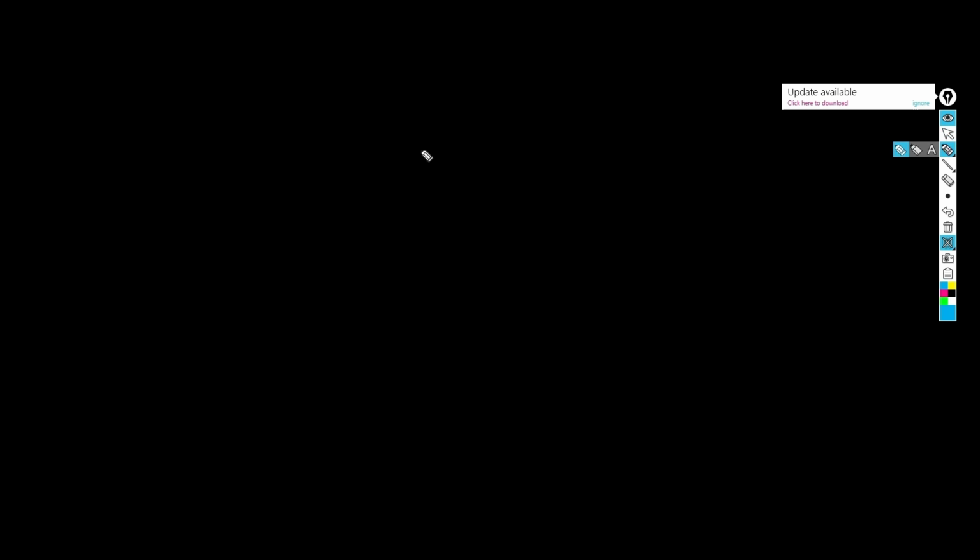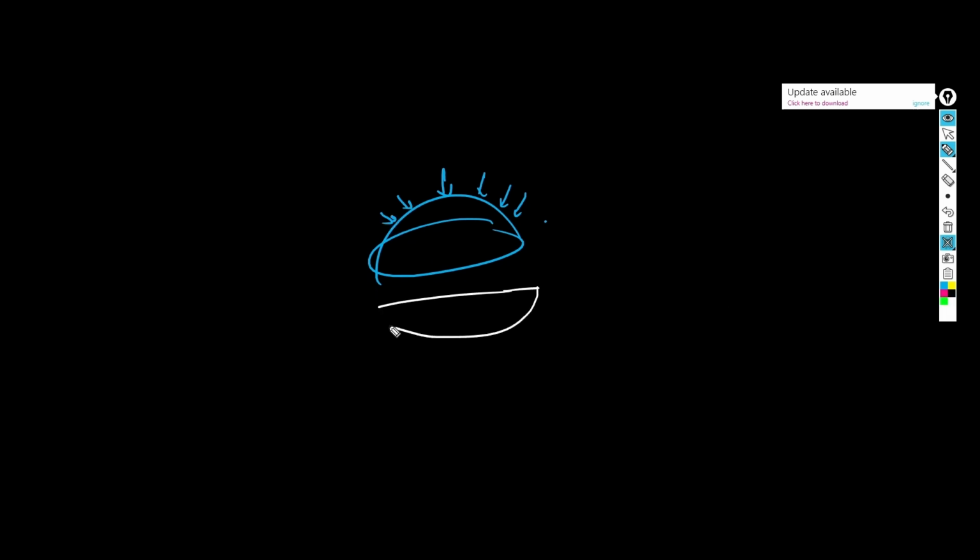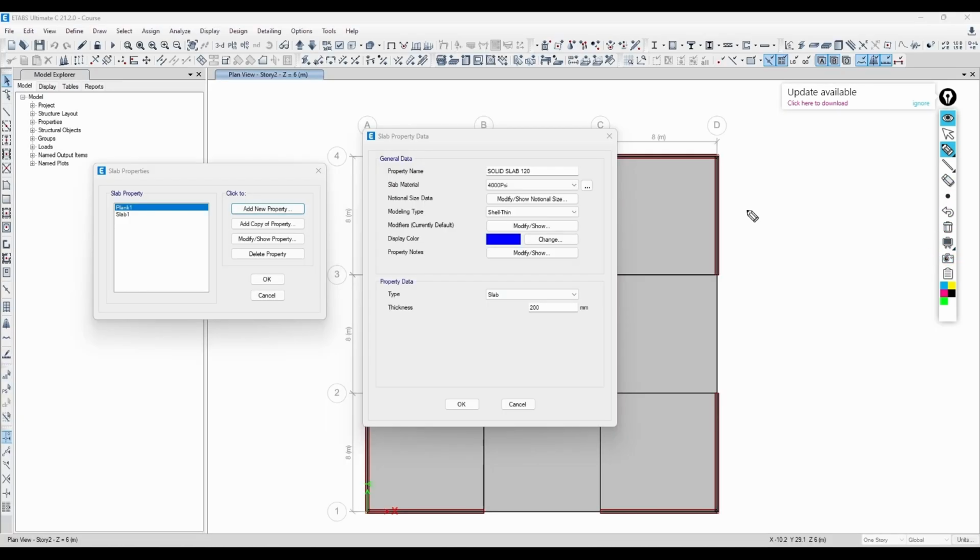So if you have, let's say, a dome, right? The dome is going to be something like this, and excuse my poor drawing right now. The dome is subjected to its weight, right? And since the shape of the dome is the inverse of the bending moment, it actually converts the flexure into pure compression, my bad. So this is a membrane. A membrane does not really withstand a flexure bending moment. It withstands a compression kind of force. So this is the difference between the shell thin, shell thick, and membrane.